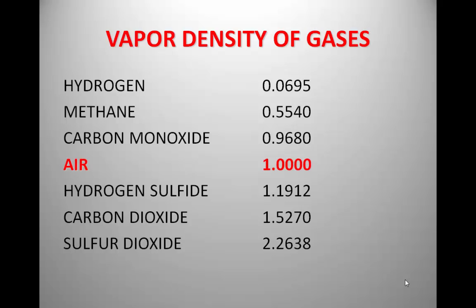Now, don't get complacent. Say you've got a space, say this space is 40 feet deep. Say it's one of our lift stations here in our district. We pop the top, and immediately our hydrogen sulfide sensor goes into alarm. All that simply means that the space is full. Okay, don't get complacent on if it's heavier than air, staying at the bottom. Obviously, if it's heavier than air and it's registered at the top, it just simply means the space is full.